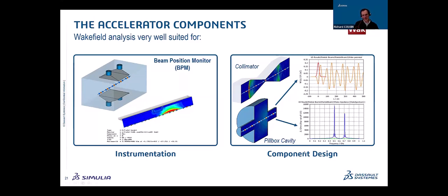Regarding now the component design, you can also use the Wakefield solvers in order to analyze the different modes or wake fields which are generated in particular structures such as collimators or pillbox cavities. So you have, for instance, on the right-hand side, the Wakefield signals that you can estimate out of the structure.